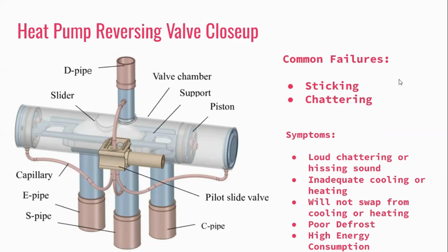It really does. These pipes down here are going to the system. This pipe here is the D pipe. This is going out of the reversing valve. Inside, this is the valve body. We call this the valve body. So this is where the mechanical movement works to make it a valve. And that's all valve body means. It means the thing that encases the thing that moves, basically.